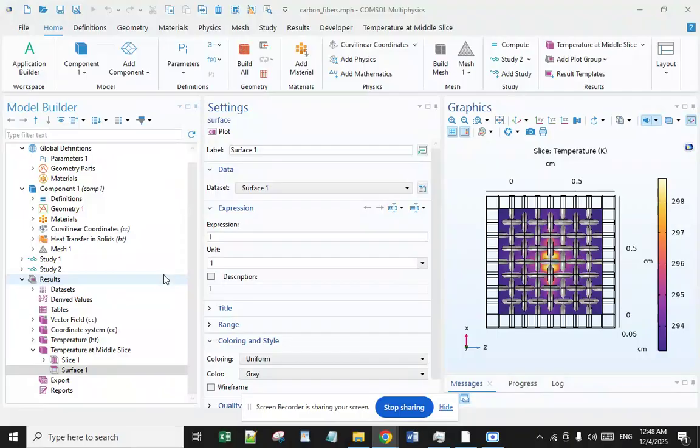A plain woven carbon fabric, A0186 000, with an areal density of 199 grams and a measured uncompressed thickness of 0.27 millimeter.